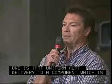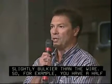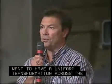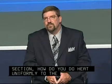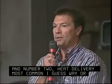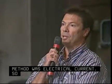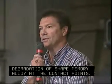If, for example, you have a 1/2 inch or 1 inch rod, and you want to have a uniform transformation across the cross-section, how do you deliver heat uniformly to the entire bulk? And number 2, heat delivery, the most common method was electrical current, so people had a hard time with degradation of the shape memory alloy at the contact points. Have there been any advances since then?